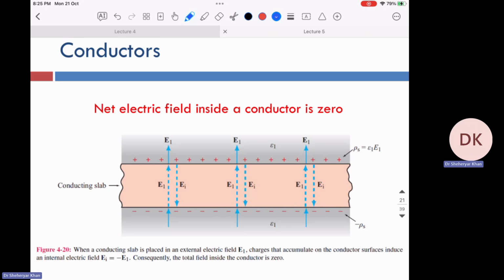If it is not present, they will strike on this, and then if you are running some transmission on your TV, if this is your video signal, you cannot see. It will produce noise, just like you have seen in the old audio transmission or video transmission or the cable transmission that requires cable. But if you have this cage over the cable, right? So this will neutralize the effect of the external electric field. So this field and this field, they cancel, and then it goes outside and the internal conductor is saved.